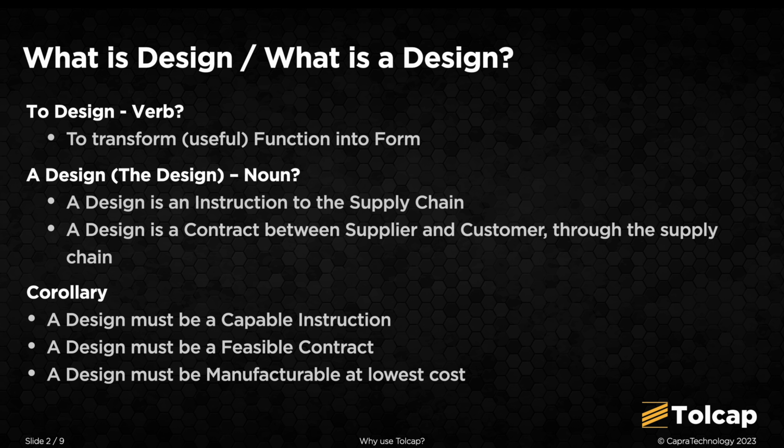But what is this design? Not just a picture of what we built and tested and seemed to be acceptable. No, a design is an instruction and a contract. Each drawing of each part in the design instructs the supplier what is to be produced. Then, if the part conforms to the drawing, the supplier will have fulfilled his contract. No one further up the supply chain, right through to the customer, will be able to say, it doesn't work, or it doesn't fit.